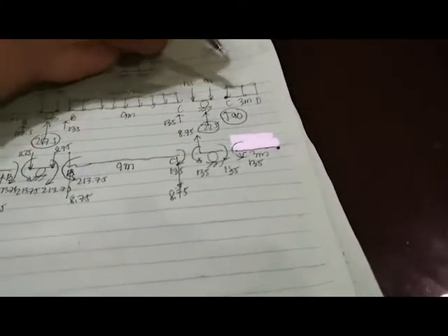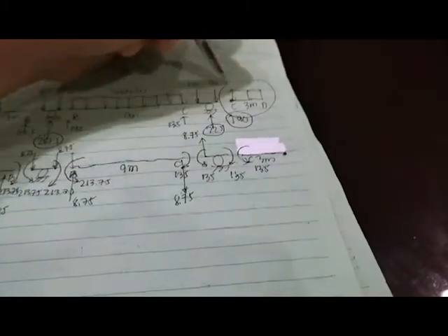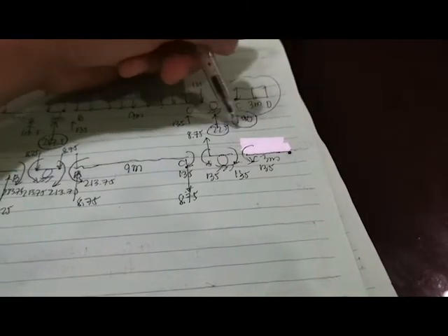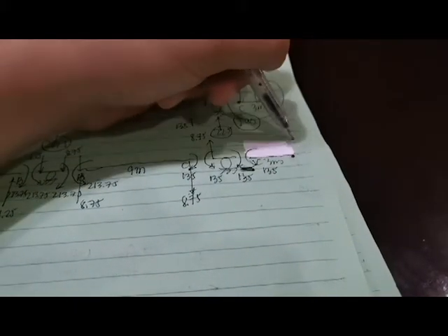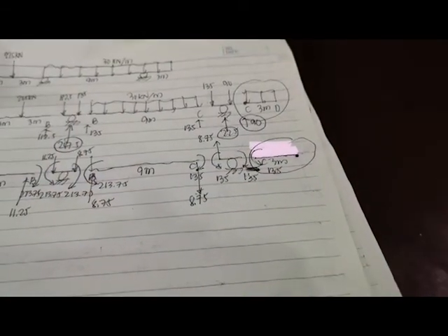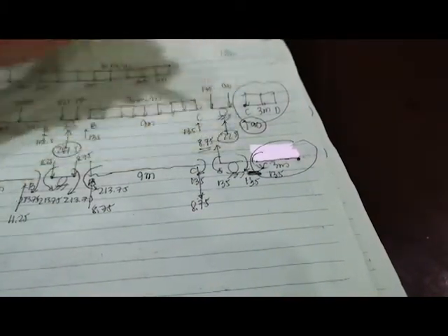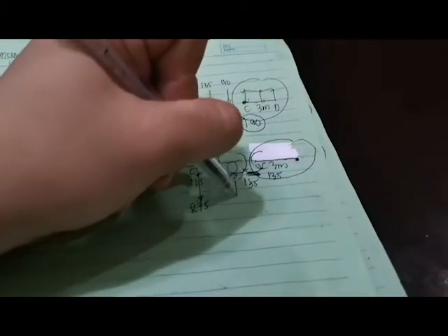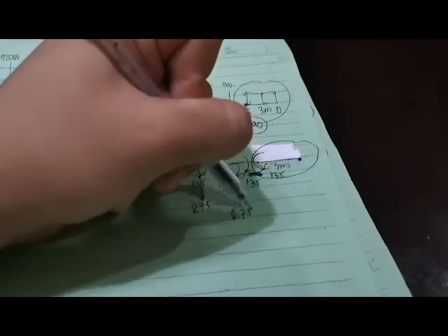Nga pala, since from the previous figure, I decided to assume that this overhang is already a fixed support, and all of its reactions are there na already. I can just neglect the reaction on this span. So ito na lang ang natitira dyan, the 8.75 kilonewton. If that is upward, we can say this is downward, 8.75 kilonewton.